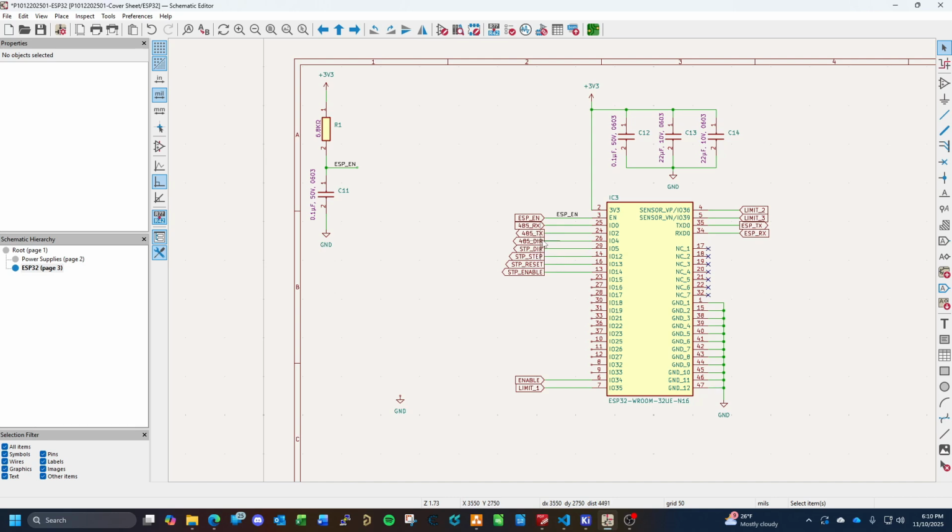So the RS-485 interface would be mainly for communicating to other subsystems, depending on how you want to program it. Because of the differential nature, you can have multiple devices connected to the same network and have them addressed internally based on their firmware. That way you can control multiple stepper motors from one central system using RS-485 over longer distances than you can get with RS-232. And it'll handle noise better. So that's why I'm throwing 485 on here.